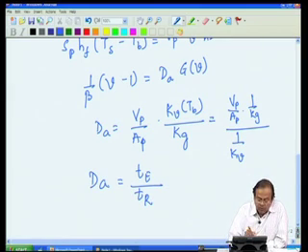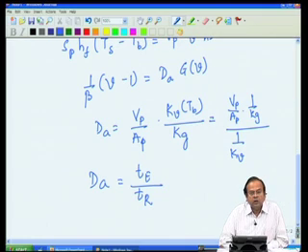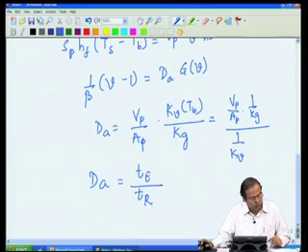So, Damkohler number Da is a measure of, or a rating parameter for, external mass transfer resistance to external reaction rate or kinetic rate, the time scales, similar to Thiele modulus which we defined earlier, which was comparing the internal diffusion process to the reaction process. Here, since we are looking at only external, we have this particular expression.